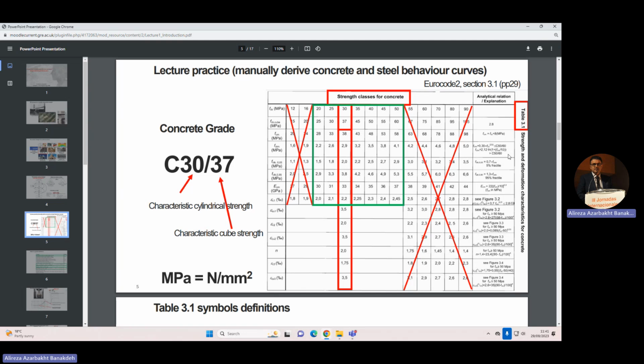Where was I? These are expensive. You use them, but in high-rise buildings. For example, if you want to make a 50-story concrete building, you cannot use ordinary concrete. You don't get the correct answers when you want to comply with the codes. The capacity is less than the demand. You have to go for the highest strength concrete. The shear wall for the Burj Khalifa in Dubai is made of highest strength concrete. Ordinary concrete doesn't work there.